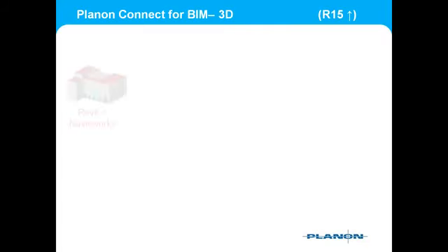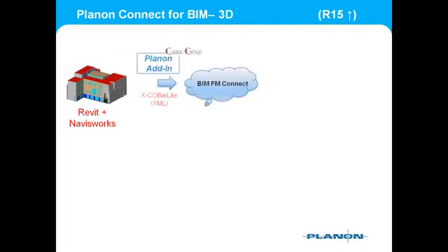Planon's solution focuses initially on the two Autodesk products, Revit and Navisworks. In these products, we will offer a kind of add-in which allows you to publish your data in COBie-like format to a cloud environment. We refer to it as extended COBie-like because we will extend the COBie-like format a bit in order to get all data from the model to Planon. The typical COBie-like format is not rich enough, but is the right standard to exchange BIM data. The advantage of using a cloud environment is that the modeler can upload the BIM data without the need to have a link or connection with the Planon environment.